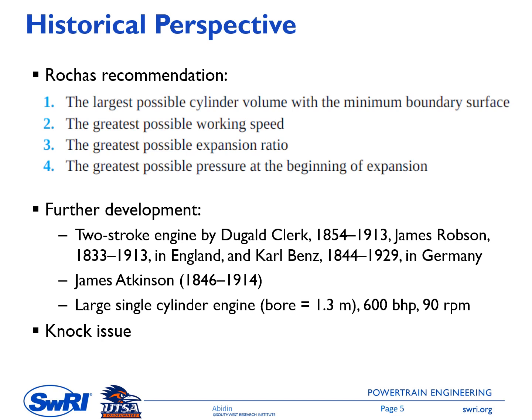What does it mean? We need to maximize the volume. It means the engine will produce higher power or higher work. You know that work is P dV. So if you can increase dV, then you will have higher work with a minimum boundary surface. It means with a smaller area, and this is related to the loss of the wall heat transfer.